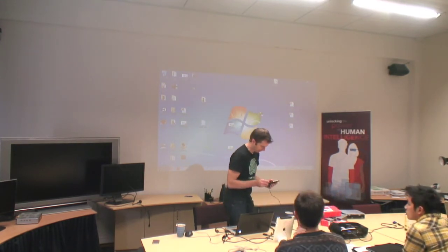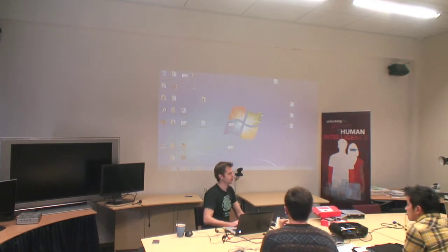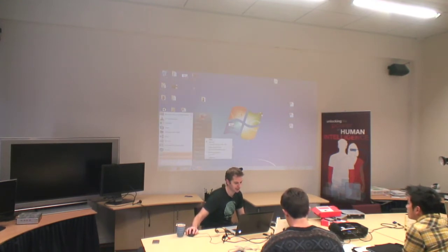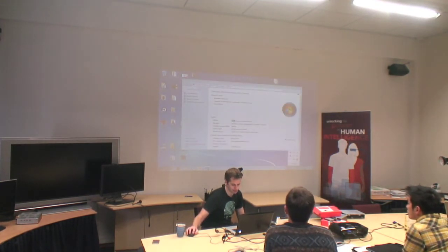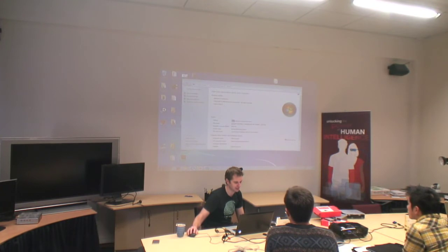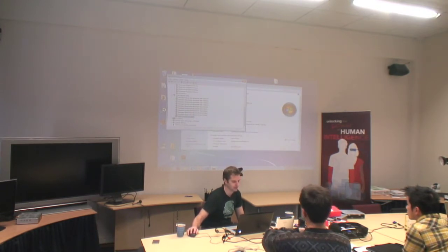So when we plug it in, you guys are all using Windows? Okay, well, that makes it easy. When you plug it in, you get the little notification and it might install some driver software. The driver should just be picked up automatically by Windows, because basically it enumerates as a USB serial port, so it's using a default Windows driver. If it doesn't work, have a look on the Arduino website, and if you can't get it working, let me know, and maybe the board's stuffed.